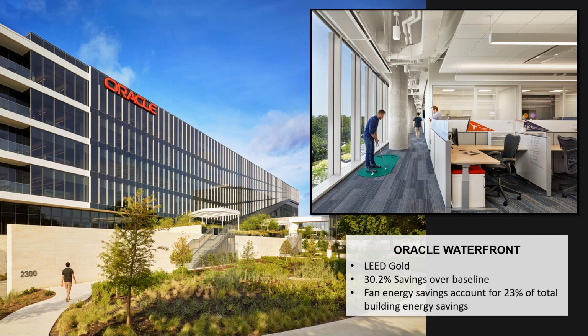And that's with chilled beams, because we're not moving necessarily a lot of air through that ductwork, and of course sizing the inlet properly, it's really a quiet system. There's no fan components or moving components other than really just the water through the coil and the water valve. So what they ended up adding in this case is a white noise speaker system throughout the area because it was such a quiet type of system.